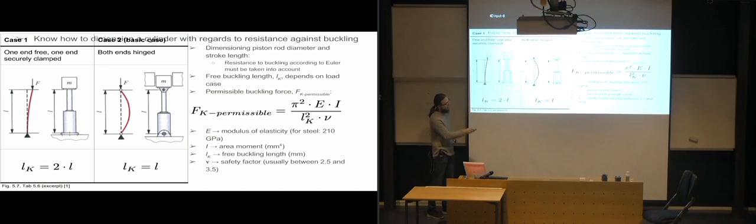And that means that the free buckling length would be 2 times the stroke length of the cylinder. Down here it's pretty much following the vertical curve until it gets up here, and then it starts swaying off. If you tried to recreate this shape, you would end up getting twice the length before you got back into a locked-in position. So if you flip it around, it's going to be twice.